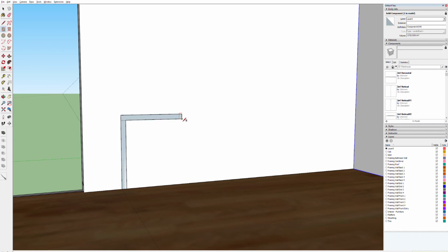All right. Now see, what I'm doing with this is that since we're not doing stringers, we need to go back down to the floor to support these things. So we need to take this, paste it over here, so we have some support. And that's going to be okay, because these are all going to be like cubby holes and little cabinets and stuff. So we're okay doing that. Now you can see with the tape measure, if I measure from here to the edge, we get 9 inches, which is our tread width. If I had made this just 9 inches long overall, then this riser that I'm about to draw would have cut into that, and we would have only had 8 1/4 of tread width.